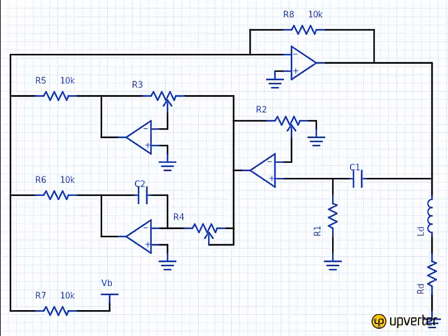The propagation delay across the 4 op-amps that we have here resulted in there being high frequency noise in the entire loop that was on the same order and actually slightly larger than the signal that we were trying to measure. And of course, if we upped the gains at every point, we would also increase that noise. So that ended up being a showstopper for us, so to speak.